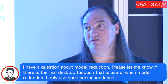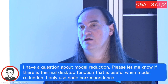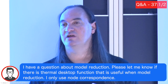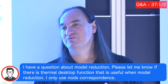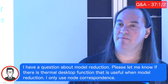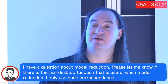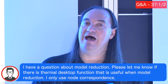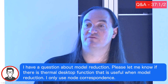Now, that said, there are things you can do if you know that you need to have a much smaller model. You could say, well, let me group together all these things that, I've got 1,000 nodes here, but the spread of the gradients is only 5 C or 5 Kelvin. So maybe I can only represent that with 10 nodes. But there is no, let me push a button and out pops a reduced model. There are people who are trying to do it, but I think that, much like correlation, is another thing that requires a human in the loop to use judgment to figure out how to best represent in a simplified enough manner while still capturing the physics of the problem.